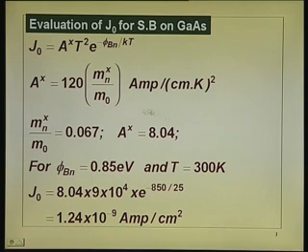That is the Richardson constant. The A star is put to differentiate it from the A that we usually use for area, so that you do not confuse area with this. It also indicates that the star is related to the Mn star, the effective mass. So, two stars related to each other. That is why it is A star and not related to area.